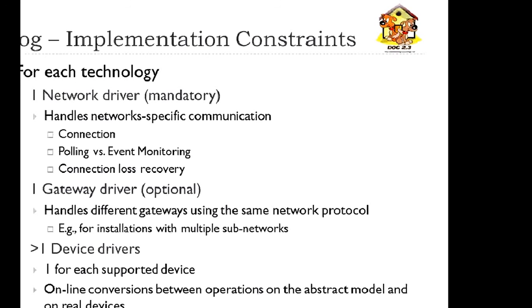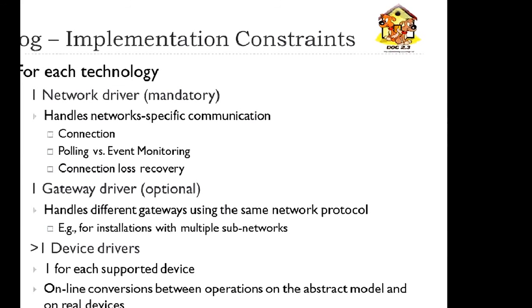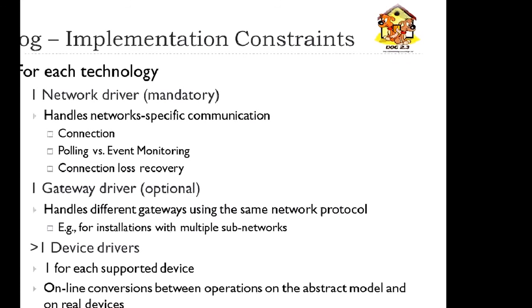Then there is a gateway driver. This is optional because we may have big installations where we have different aisles of technologies. Every aisle speaks with the central system using a gateway. Then we will have just one network driver, because it is the module that knows how to communicate with that kind of network, but many gateways.